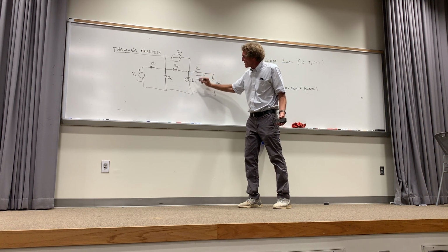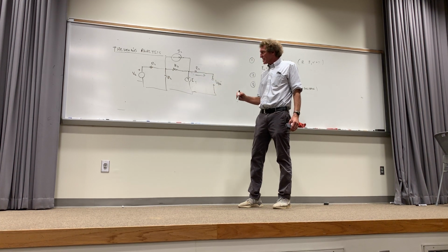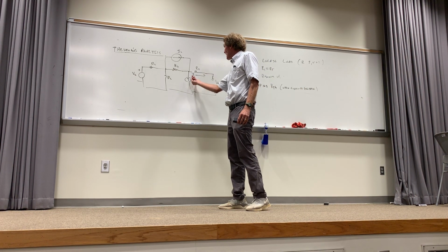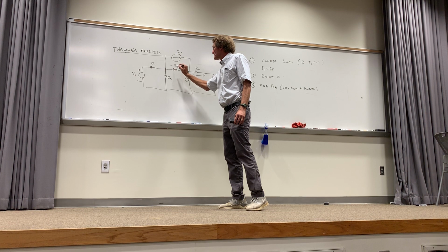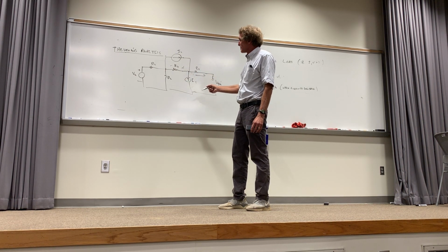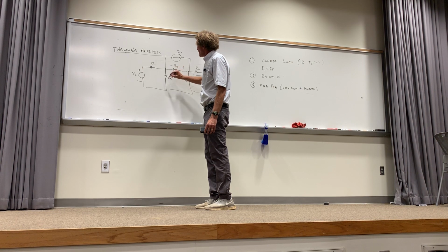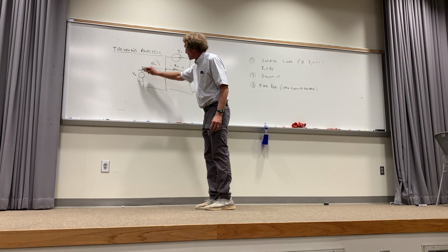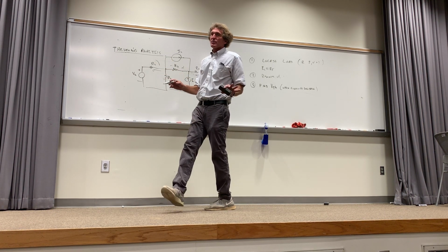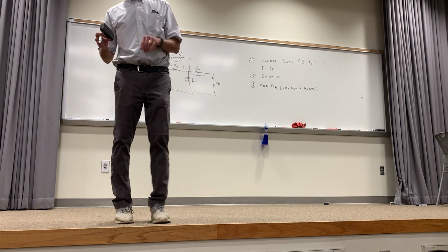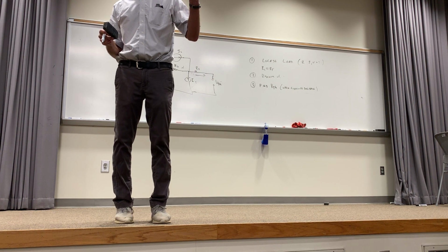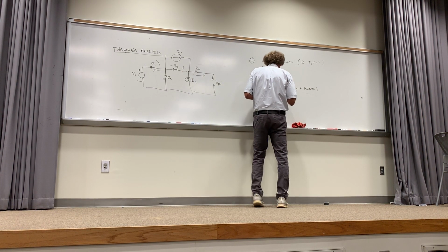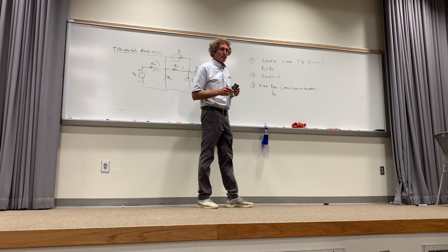That means the voltage across this is the same as the voltage across this. And I'm not going to get this for this circuit, but we could get this voltage pretty straightforward because we've got I going there, I going there. That means this voltage here is R3 times I2 plus I1, right? And then comes here, then you get current division here and here. Well, actually, it'd be a little more complicated doing this part, but you could do a source transform there. Anyway, when I do a real problem, I'll go through it, but you could easily get in most problems VTH, the open circuit voltage. Got me? I think in the book he also calls this V open circuit. So this might be V open circuit. They're the same. It's the open circuit voltage, right?